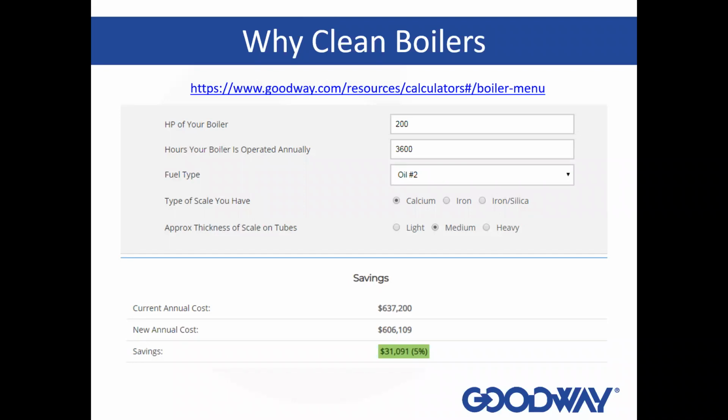And we'll discuss a water tube boiler first. On the inside of those tubes, the boiler is a great source of evaporation. It's throwing a lot of steam. You get mineral fallout happening on the inside of the tubes. That acts as a great heat transfer insulation type of effect, and so the efficiency of the boiler is reduced.